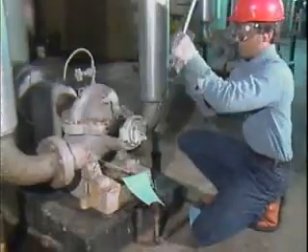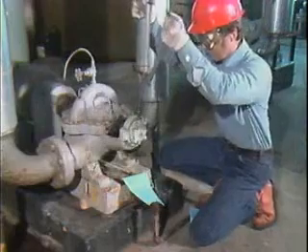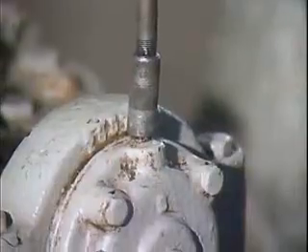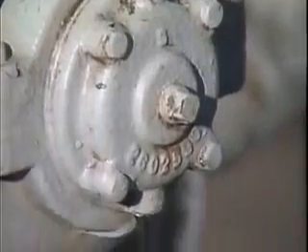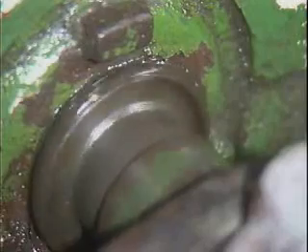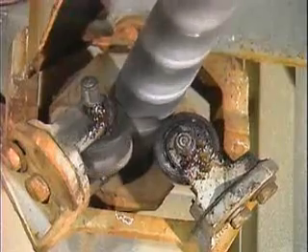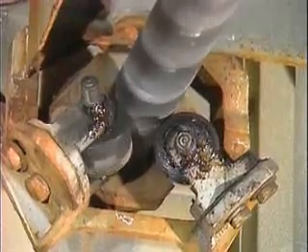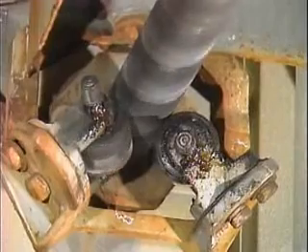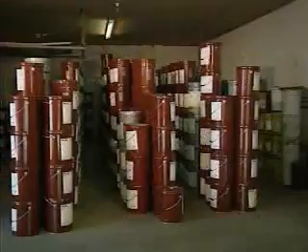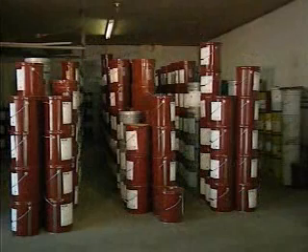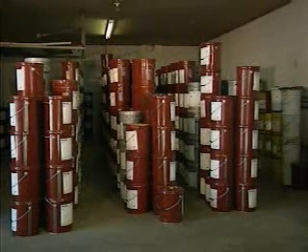A grease's consistency or stiffness is an important physical property for much the same reason as drop point is. If a grease is too hard, it will be difficult to apply. But if it's too soft, it may flow away from where it's needed. Either of these situations could result in inadequate lubrication and damaged equipment. The consistency of a grease varies with temperature, and there's generally an increase in the softening of a grease as the temperature increases. For these reasons, consistency is a critical property to consider when grease is selected for a particular application.